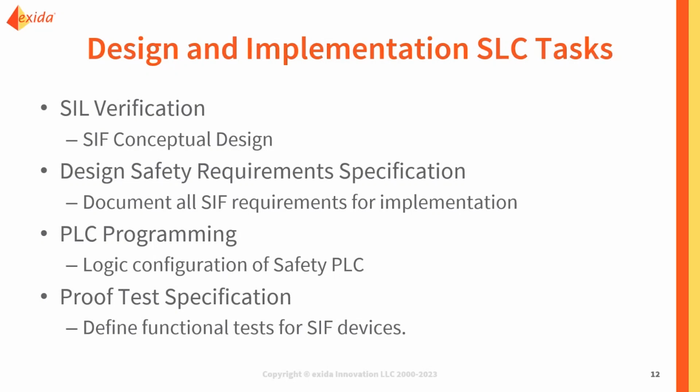Another output of your SIL verification is the ability to automatically configure your safety logic for a Delta V system. Within exSILentia, we're able to, in Silver, define the inputs and outputs and the relationship between them. And so we're leveraging much of the work that you've already done to help you get started on that configuration of the safety logic for Delta V. So we have a tool that creates an FTX file that you can then bring into Delta V, and it will configure your safety logic for you.